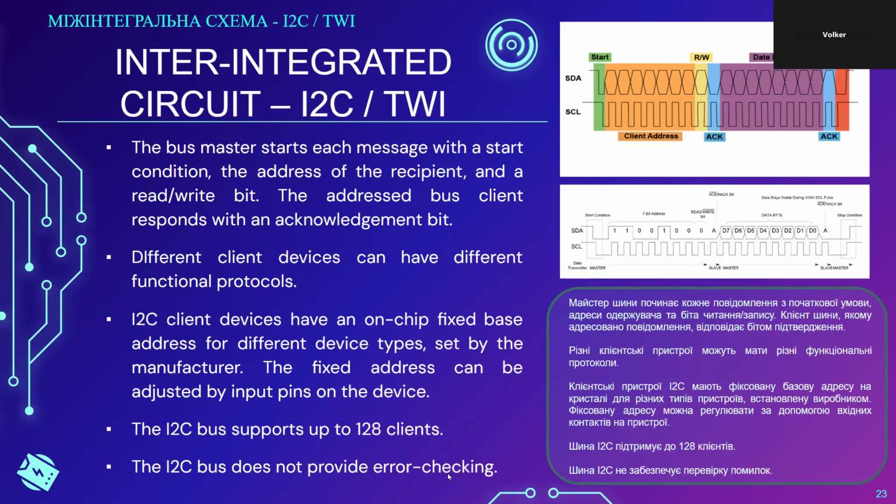I don't want to get too much into the details of the I2C bus here. I just want to point out that this is now a protocol. This is not just two shift registers like the SPI bus that are basically connected in a circle. This is a protocol that has states.